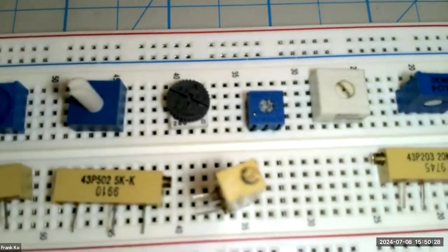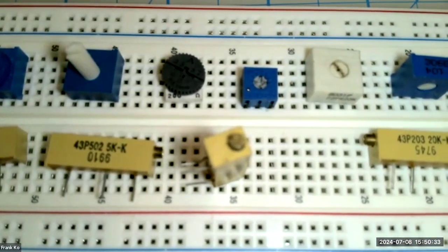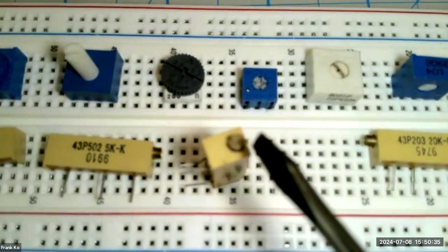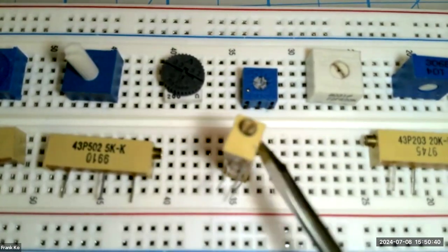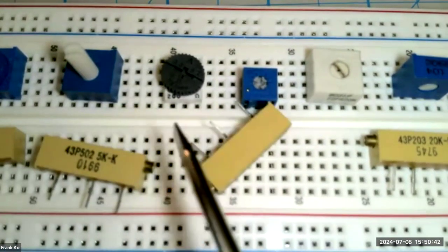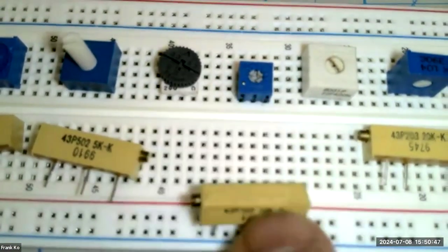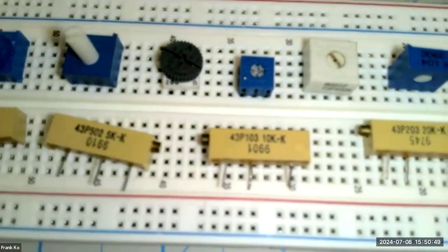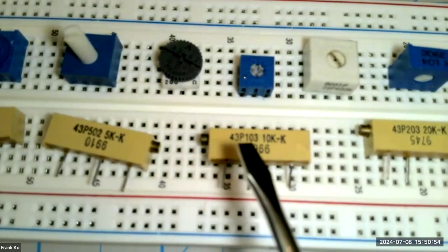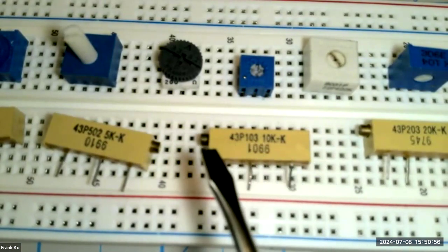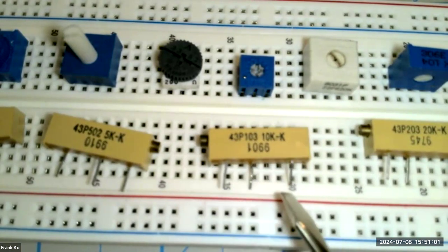It's focusing on the other part of the board, sorry. Anyway, there is a screw post, trust me. And if I bring a screwdriver in here, I rotate this, I can get anywhere between 10, 12, and 15 turns of pot rotation in order to get from one extreme to another. So what does that mean to you? What that means is with a multi-turn pot, you will be able to get more precise and gradual adjustments of your resistance between the middle pin and one of the outside pins.